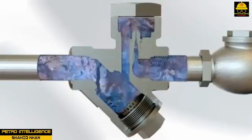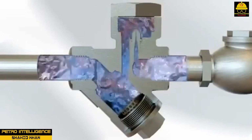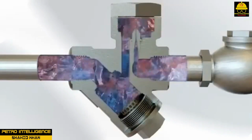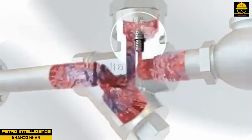Steam traps are also used to remove air and dirt from steam systems. Trapped air is especially dangerous in steam systems because oxygen in the air can oxidize steam lines. Over an extended period of time, this oxidation process will eat through the steam pipes and create severe steam leaks.